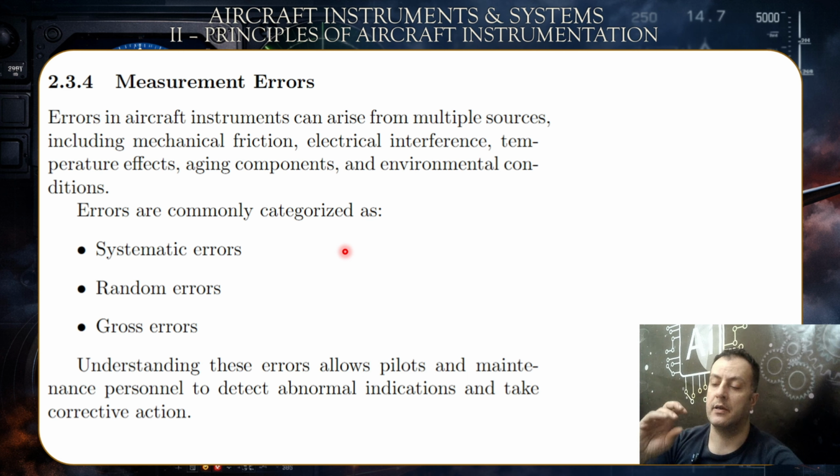For example, a resistor, a capacitance, a diode has worn out, so it would lead to an error within the measurement, like a resistance that measures the temperature has broken off. It would display an overheat. Why? Because it has suddenly become an open circuit. So it would be something within the instrument or the sensors. That would be the systematic errors.